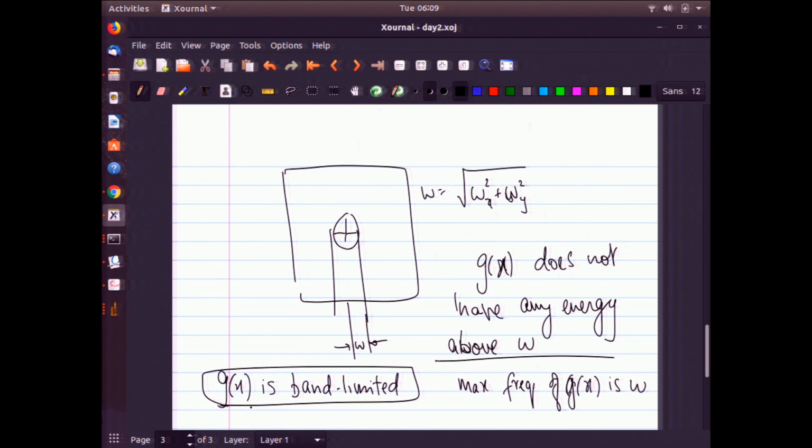What we're saying is this frequency spectrum is often called a band because you see bands of energy. And band limited tells you that there is a limit to where the energy can be for the Fourier transform of this function. So anytime anybody says band limited function, this should pop up in your mind, right?